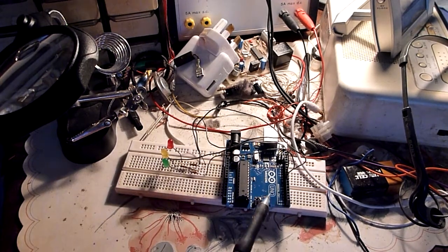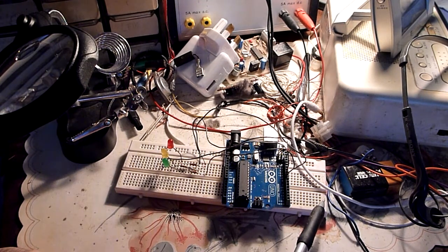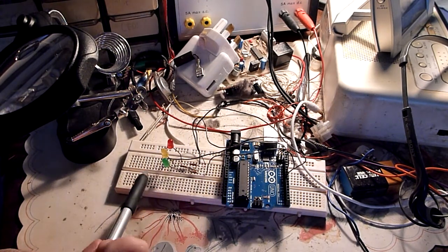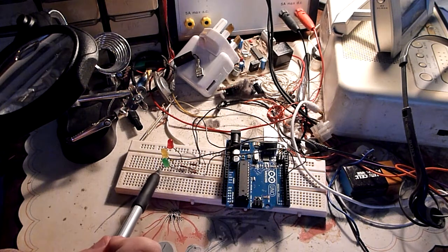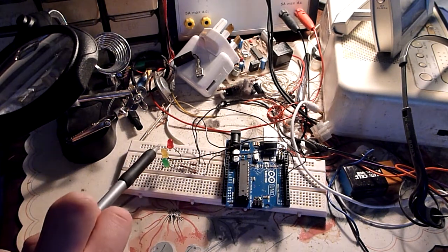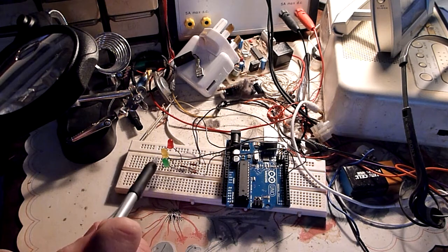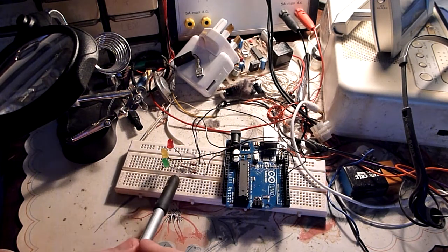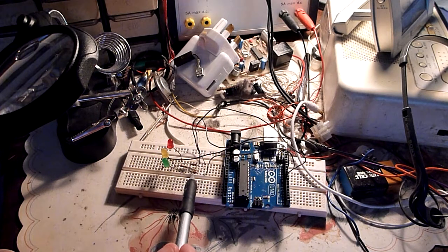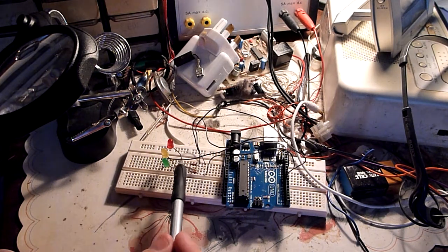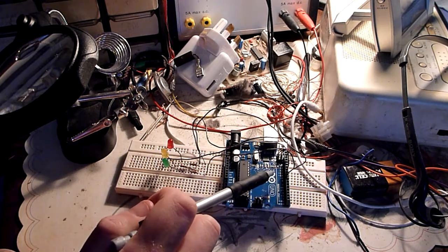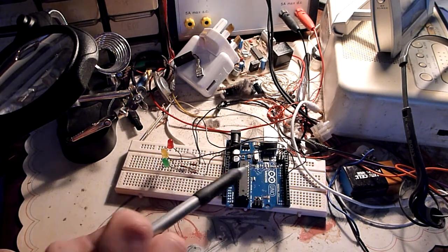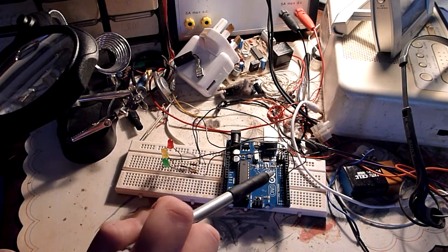So here's the Arduino board. I've got a breadboard here on which I've placed it. I have my three LEDs. The cathodes are wired onto the ground pin. So that's the one with the shorter lead or a little tab at the back there. That's the negative part, if you like. Three resistors, 220 ohms, onto the anodes. And I've wired the red into pin 10, the yellow into pin 9, the green into pin 8.